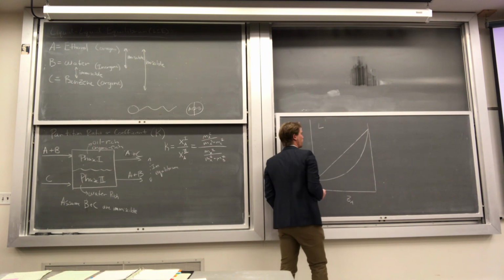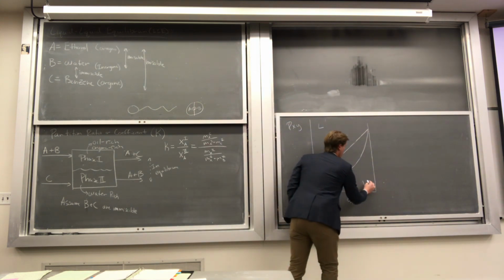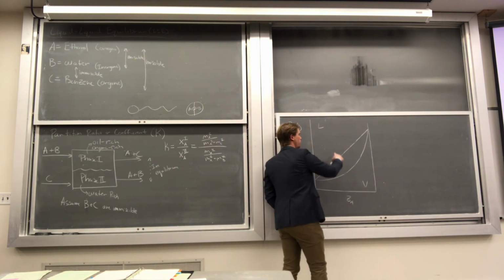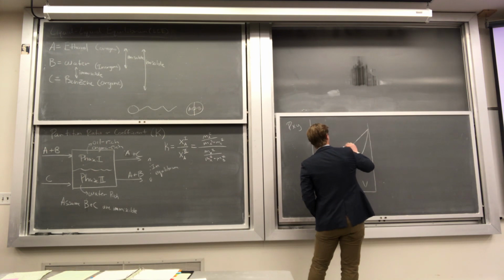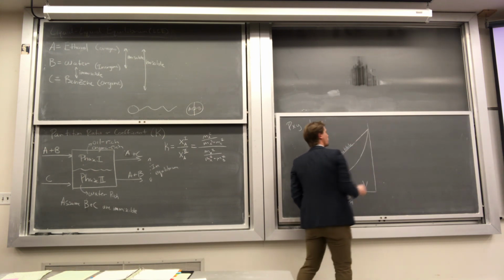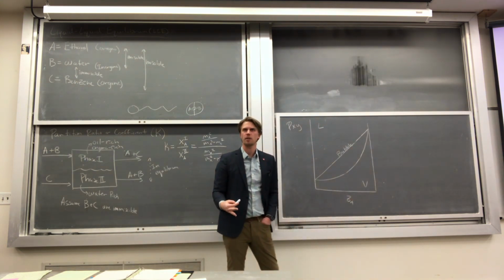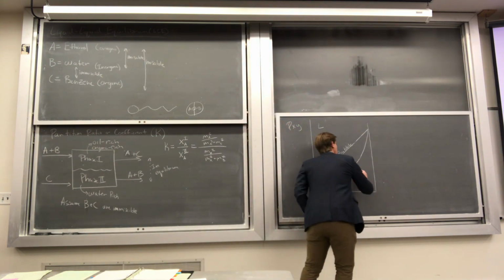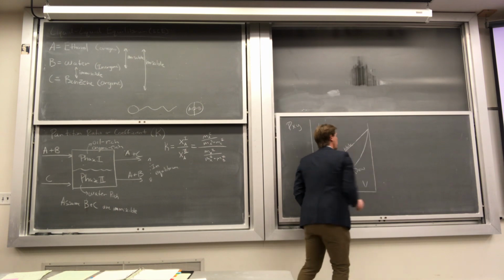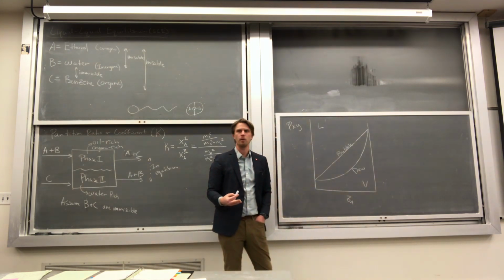At low pressures, what phase am I in? Vapor. So this line here going from liquid to the 2-phase is called what? This is the bubble curve. The bubble curve tells us information about the liquid phase composition. Going from vapor to the 2-phase region, this is our dew curve. The dew curve tells us about the vapor phase information.